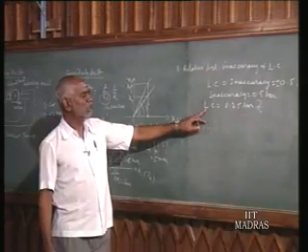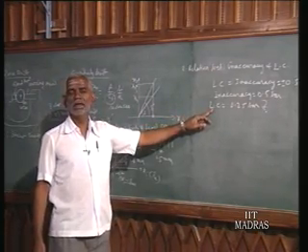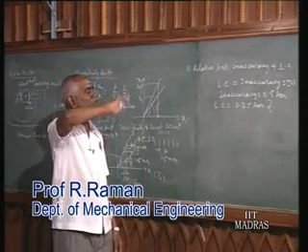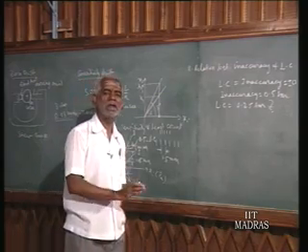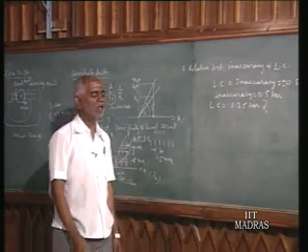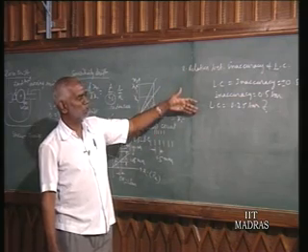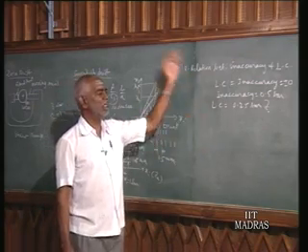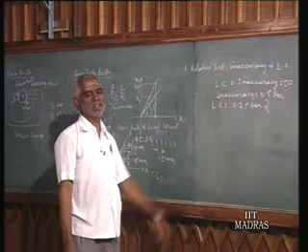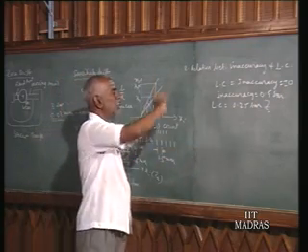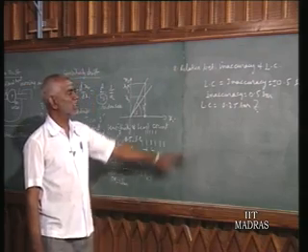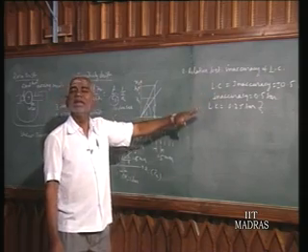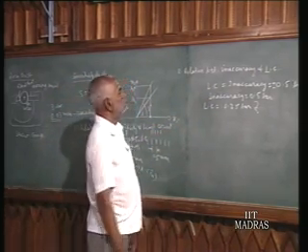Even though we can have finer and finer least count, the simple way of achieving a finer least count is to increase the pointer length to any length you require, and you can have a very fine least count. But that is not permitted, because the inaccuracy is much larger. Hence, you cannot increase the length of the pointer alone as you like, because inaccuracy is larger after a certain increase of the length. So, that is the limit for getting a finer least count. The inaccuracy within the instrument puts a limit on the least count. I think with this we can close it today.